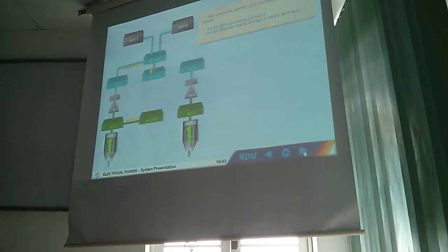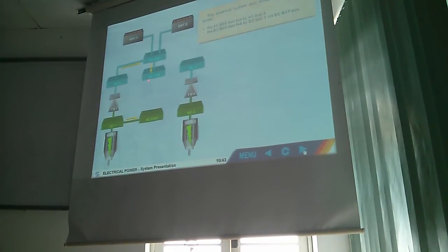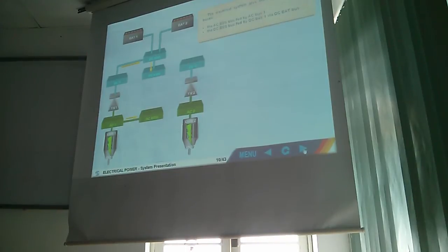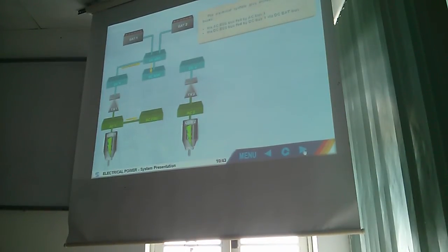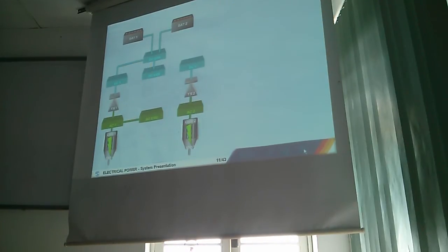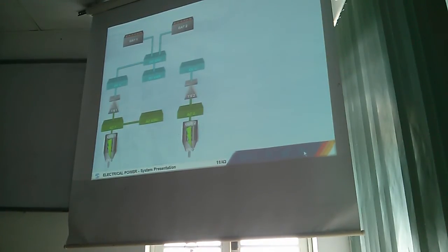So that also means, of course, that the battery can also feed the DC essential bus directly. No generators online. Now your battery is feeding your DC essential bus. Okay? And if you do that long enough, no more power. So this is the basic electrical system.